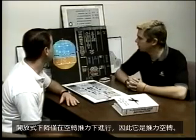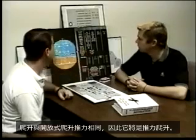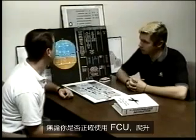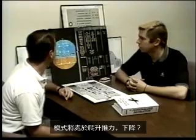Open descent: thrust idle, open descent. Open descent is only done in an idle thrust, so it's thrust idle. What about VNAV climb or your climb FMA? Climb is the same thing as open climb for us, so it's going to be thrust climb. Regardless of whether or not you're using the FCU properly, the climb mode will be at climb thrust.